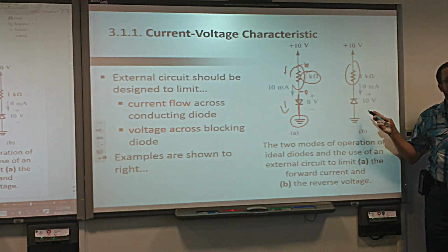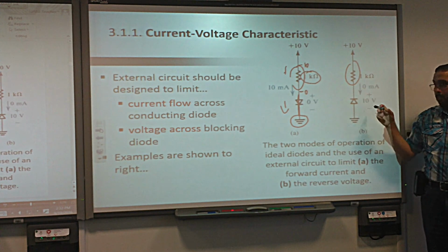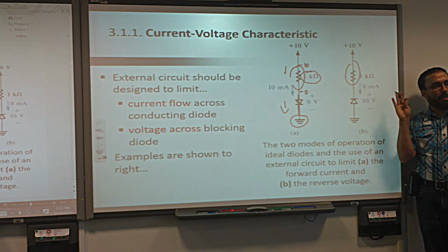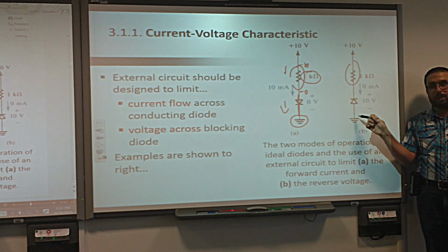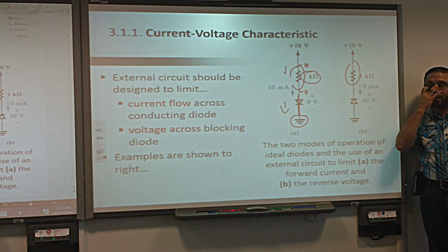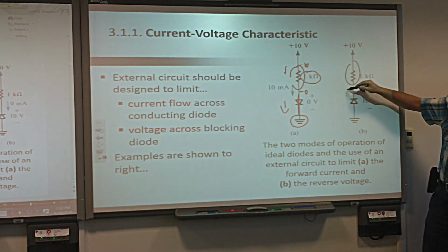Now in this case, see what we did? We just flipped the diode, yes or no? Want to flip it? So basically automatically it will be without any thinking, because now we put this guy in the lowest voltage and this one is the highest, connect to the highest, yes or no? So automatically it's reverse. So replace it with what? With open circuit. Very good.